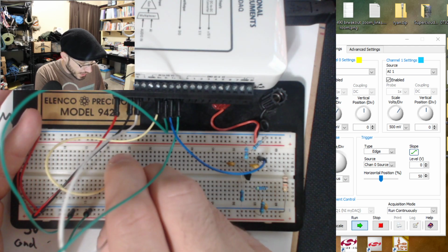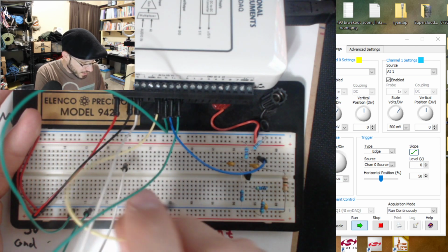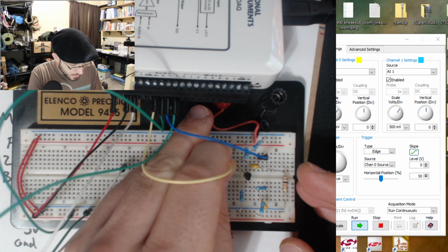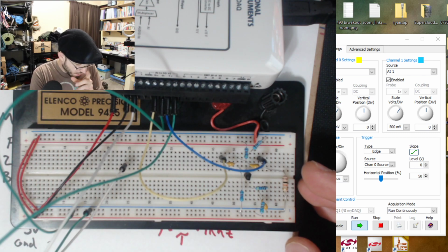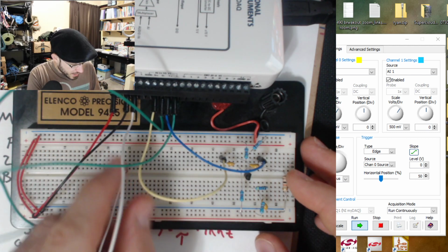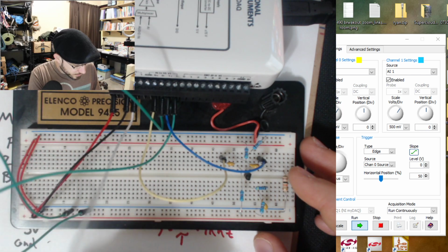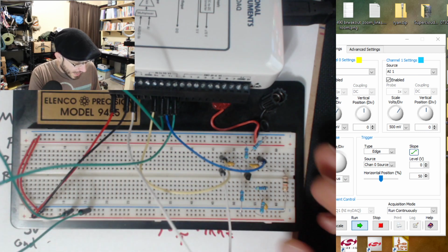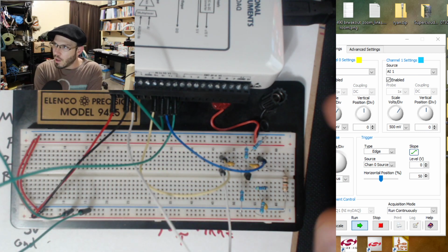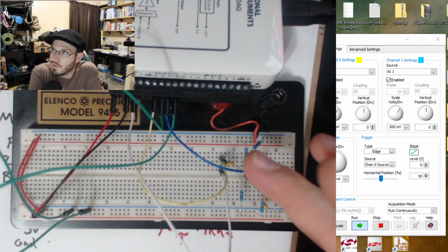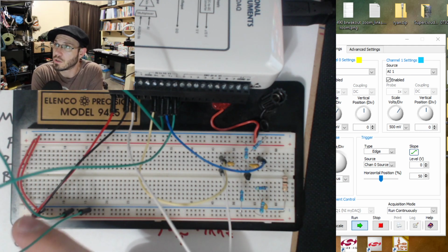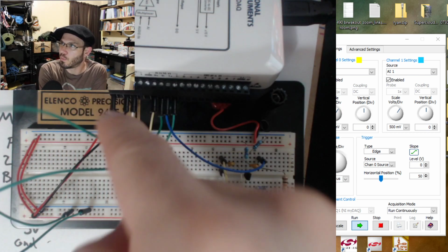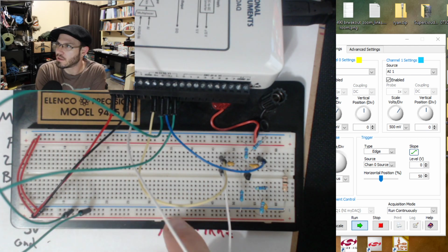I'm going to take my channel 1 of my oscilloscope and hook that up to the input of my circuit, and I'm going to take my function generator and apply that there as well. Now, my common emitter amplifier circuit is running off of 15 volts. It is getting that 15 volts from the board. Sorry, from the MyDAQ through the red wire to the positive rail.